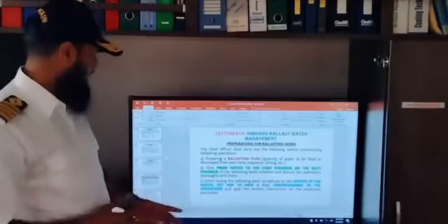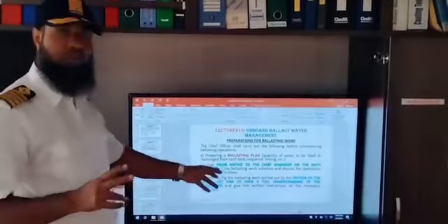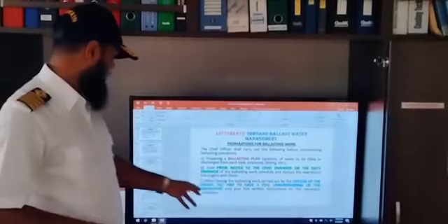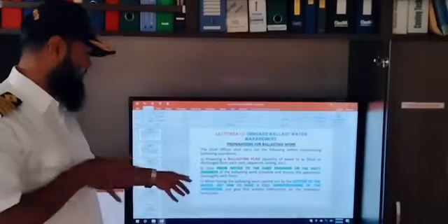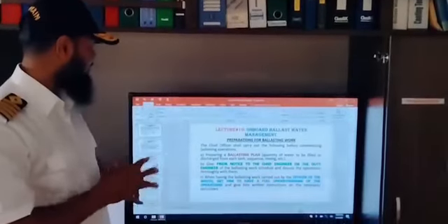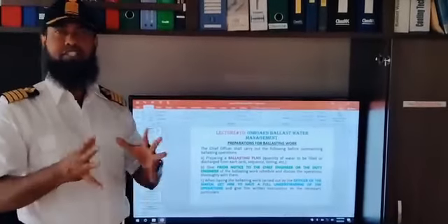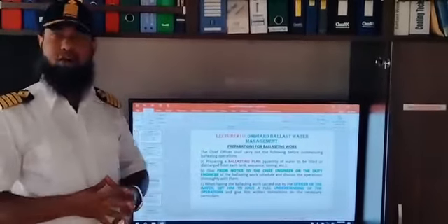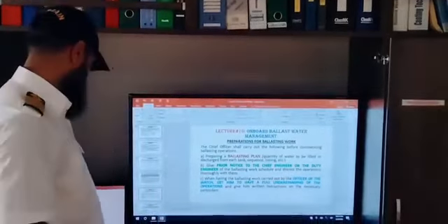So at that time, he will prepare the plan, either a ballasting or deballasting plan, and of course he will give notice to the engine room. Also, when the ballasting work is carried out by the officer of the watch, he must have a full understanding of the operation, which means when the officer of the watch is involved, he must be well acquainted with this operation procedure.